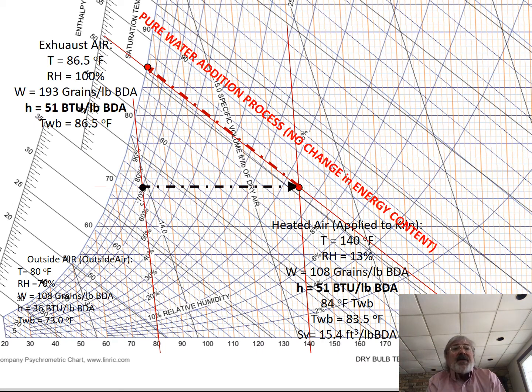So back to this. If I'm starting my kiln up, I'm definitely in the constant rate period, the constant drying rate period. So I know now that my air is leaving the malt bed at 100% relative humidity. So that gives me the other point. I'm somewhere on this line at 100% relative humidity. This is where my exhaust is. All right.